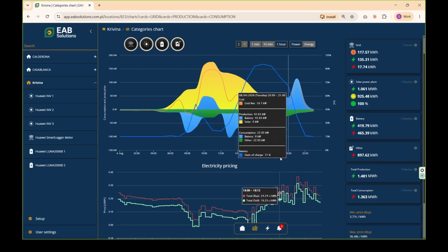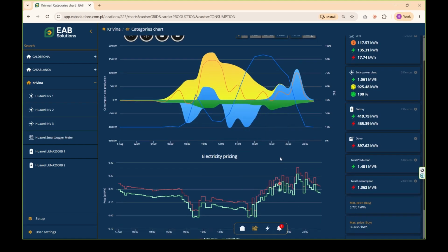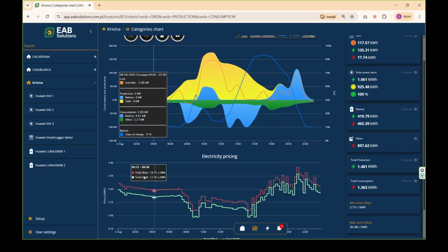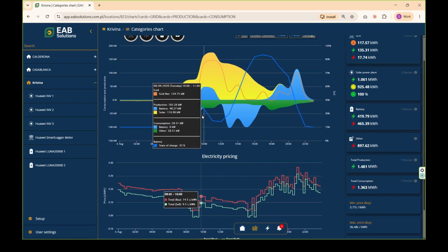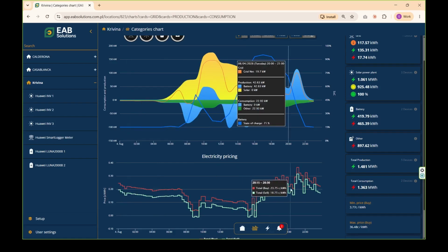What happens? In that case, there's no problem at all, because as we said, we load the electricity prices the day before, so we already have the schedule planned and calculated for the following day. That is, the day before we've done the calculations for the next day. So the EMS already knows what it's going to do tomorrow. It doesn't matter if today, after downloading the data, it lost its internet connection for hours. It would already have defined its schedule.